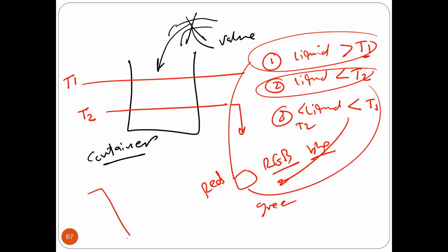All what we have is PP4, I guess, right? PP5 and PP6. Number 1, I have to configure these 3 bits as output. Number 2, if I want to turn this color on, I have to put here 1, and I have to make sure I put 0 here, right? If I want to turn this one on, I have to put here 1 and put 0 here, and so on. Is that okay?